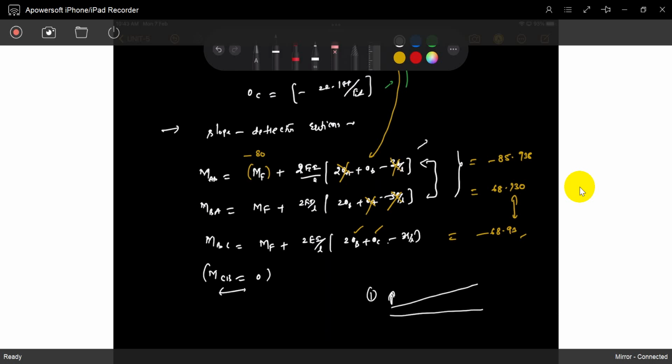It is not stable. It will give some deformation or some rotation. You have to find the deformation here and the rotation here. If you give a unit force, how much deflection you get, that is the flexibility matrix. You can't find those values because it is not stable, but it is workable in some computer programs. No one uses it, it is imaginary.